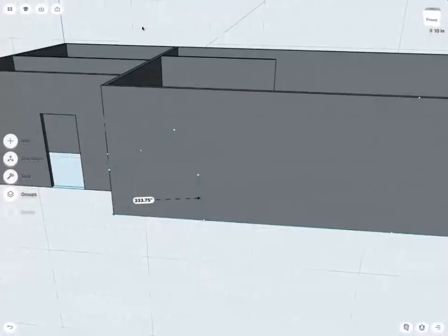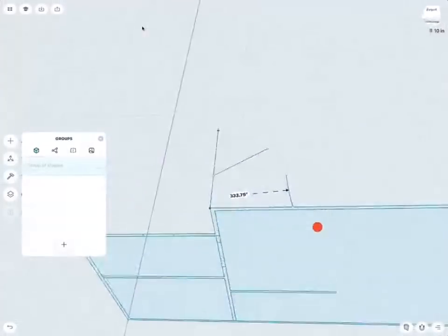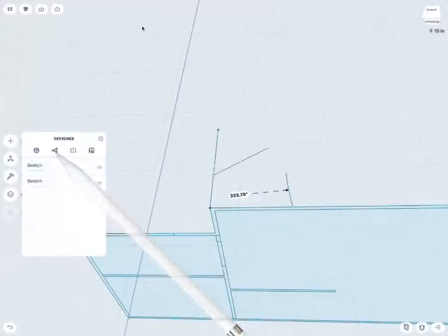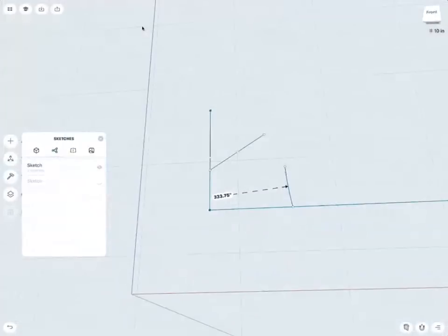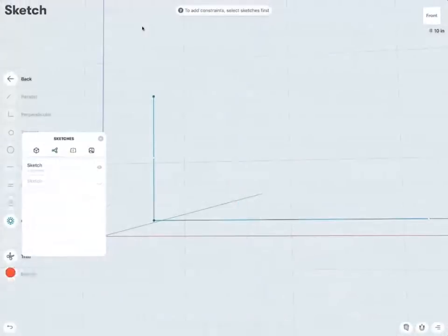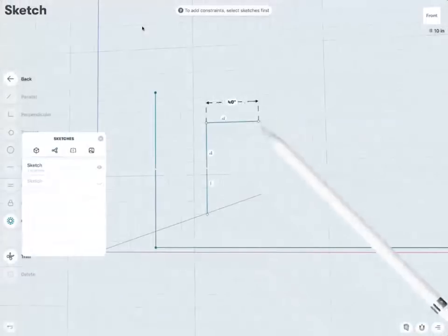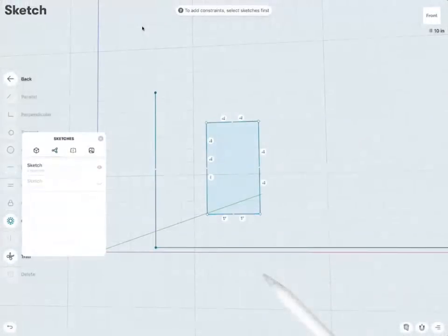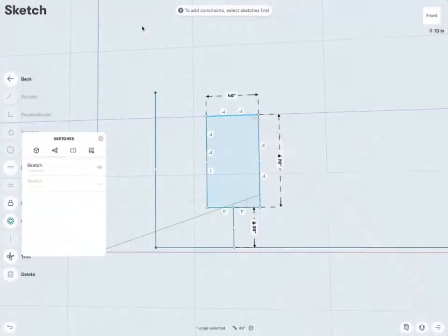And the reason why I did this is if I hide now the geometry, you see it copied out the left and the right edge. So this is the left wall and the bottom edge. These lines I can delete. And then I could draw a window, let's say 70 by 40. Very nice. And either via a dimension or simply via a line, I can then specify how high that window should be.